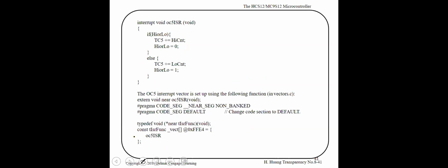So this is the interrupt service routine, and here the example uses the large memory model, and we talked about this in chapter 6. When writing C programs, we said we need to specify the memory model. For small models, we said there is a different way to define the interrupt service routine when it comes to large memory or segmented models.